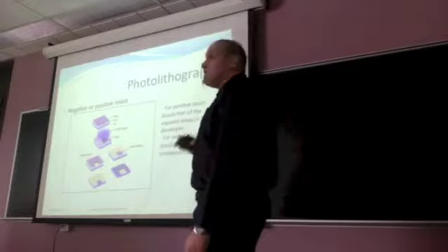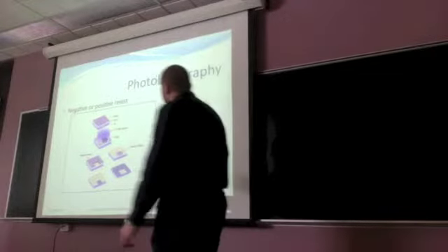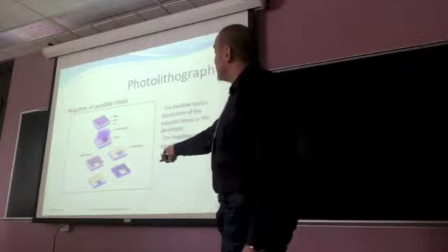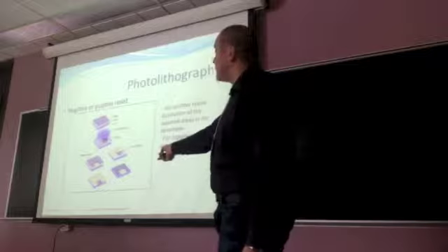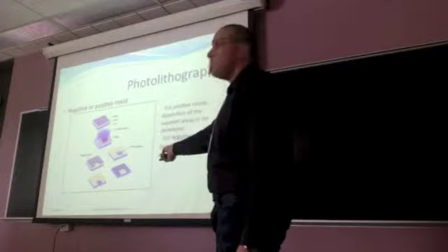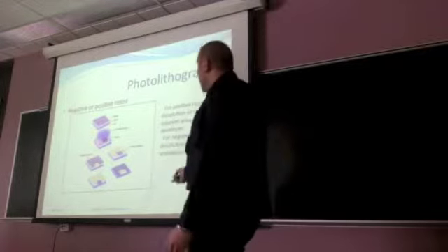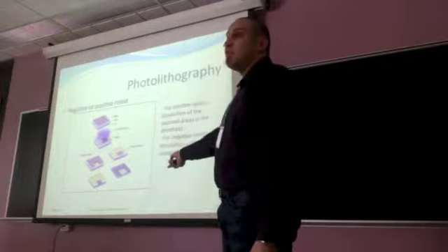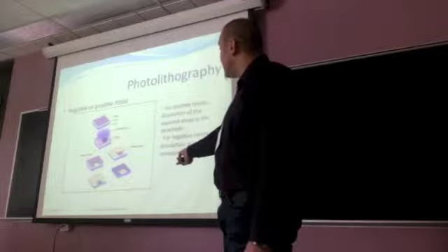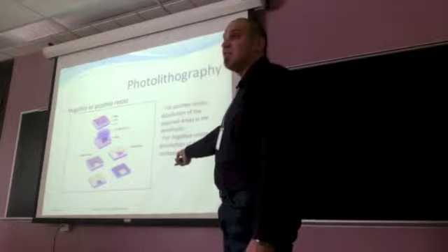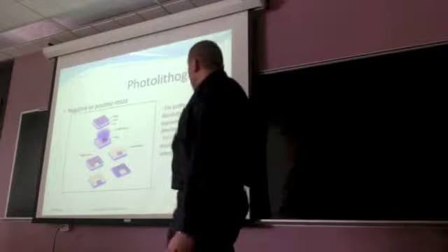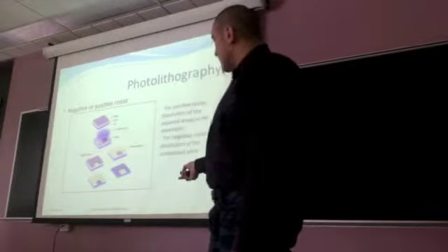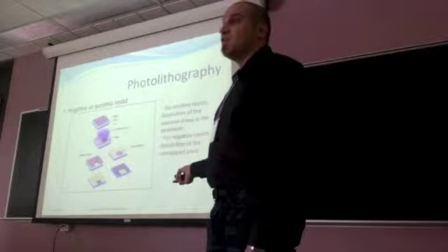So on this sketch here, you can see a photomask with a square chromium area. So this area will block UV light. So for a positive resist, the exposed area of the resist will be dissolved in the developer. So you can see only this part will stay after development. Whereas for negative resist, the non-exposed areas of the photoresist will be removed in the developer.